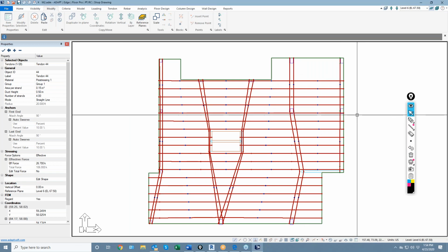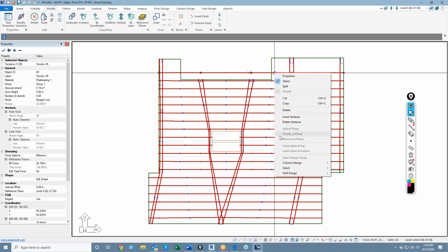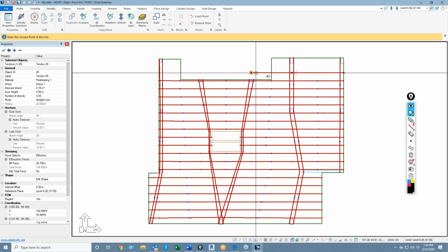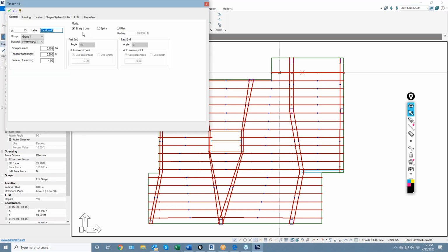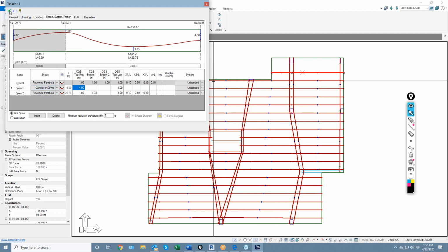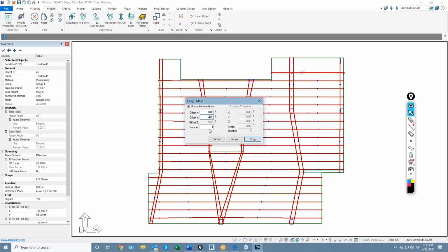And then the last part will be up in this area here. So we'll go ahead and copy that up. Again, I don't have to copy. I could just draw a brand new tendon. The reason I copy is just easier for me to edit the cable than anything. So remember, this right now is a reverse parabola. It actually is copied from this span, which is a RP shape. So we're going to go back and modify that to cantilever down, and then copy that tendon up just a couple of times.